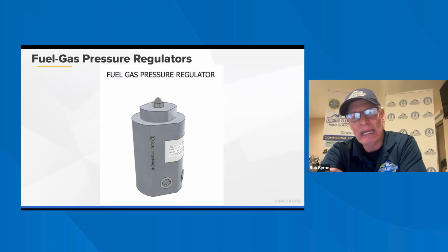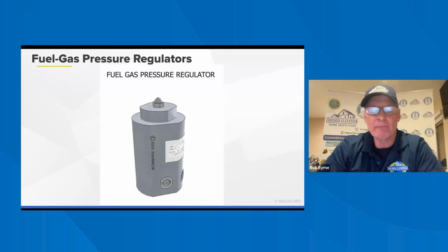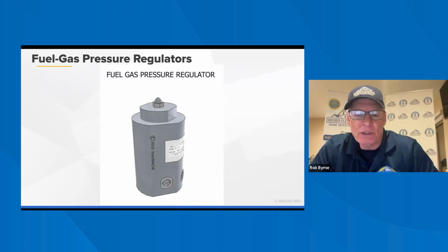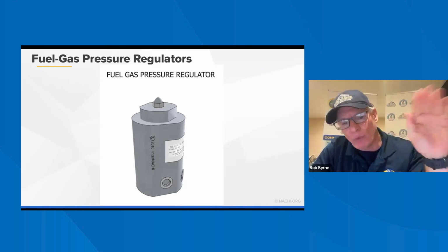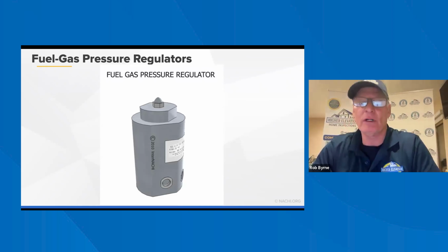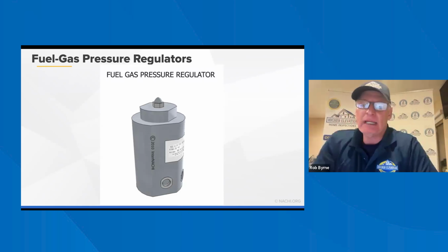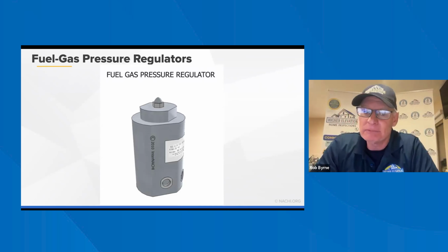Now, here, when we have a gas meter that's inside the house, you should see that vent going outside the house, because it's high pressure gas and there's a regulator on it. So if there's an overpressurization, it'll go through that regulator and wind up going outside and venting to the outside. So that's important. If you come across a gas meter inside the house and you don't see this, I'd be shocked, because the gas company's all over that. Unless it's real old, look for that. And you'll see it outside.